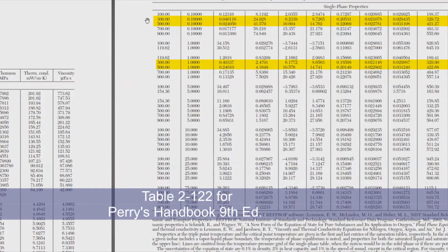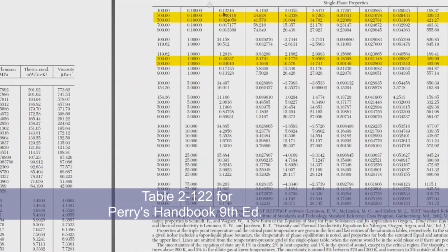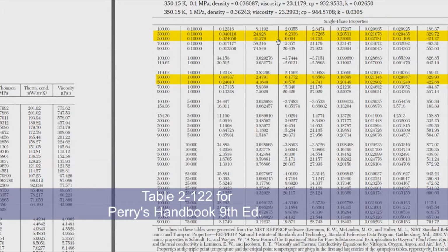With that, since this is what we call the double interpolation, after interpolating, we'll be interpolating again in a way that we'll be considering the difference in pressure, since we'll be interpolating between 0.1 and 1 at 0.2026. So upon interpolation, what we will be getting are these values. I won't be showing you how to double interpolate since you should have known that. But if you're not familiar with how this interpolation works, this is how we do it.